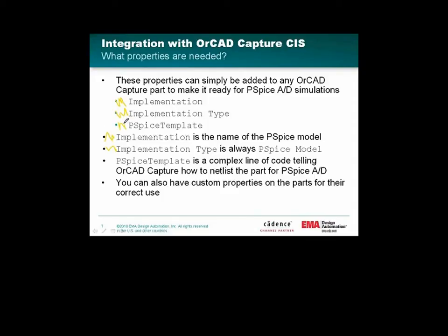And PSpice template is a line of code that tells Capture how to netlist that part off so that PSpice can understand what's going on. It's kind of a complex line of code. In Capture, it's a property, and it tells it how to netlist it off to PSpice.